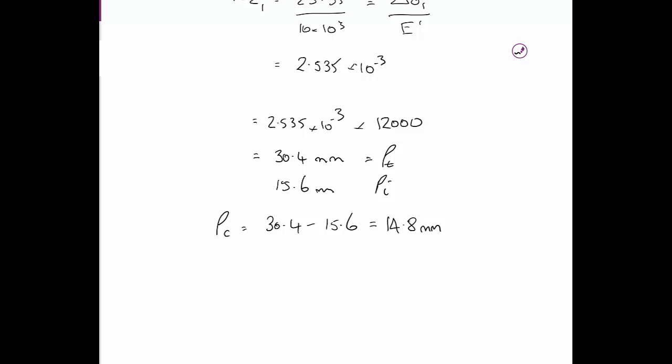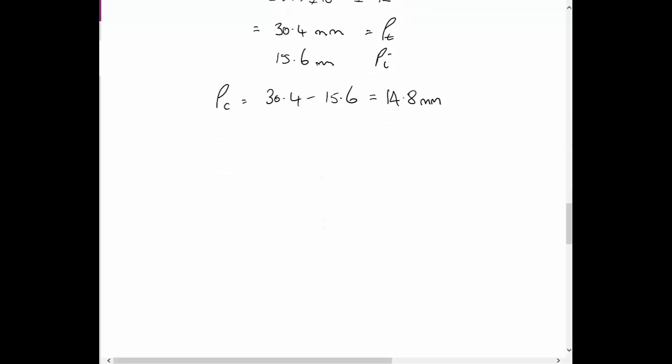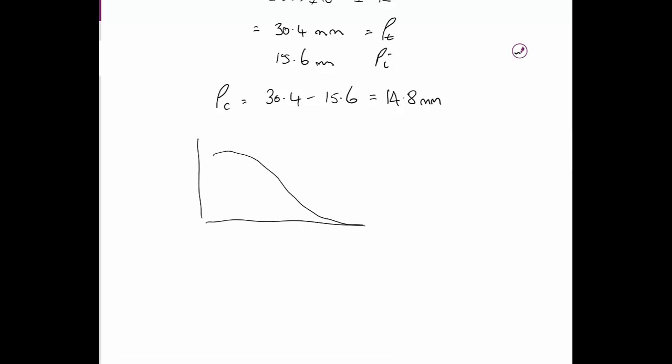Now there's another type of settlement. What happens? If I can quickly draw a sketch here that hopefully shows you a consolidation curve where that's 100% consolidation. So that's change in stress, and that's settlement, and 0% is up here somewhere. Don't need to really worry about that. But after 100% consolidation, you'll see here that additional settlement occurs.